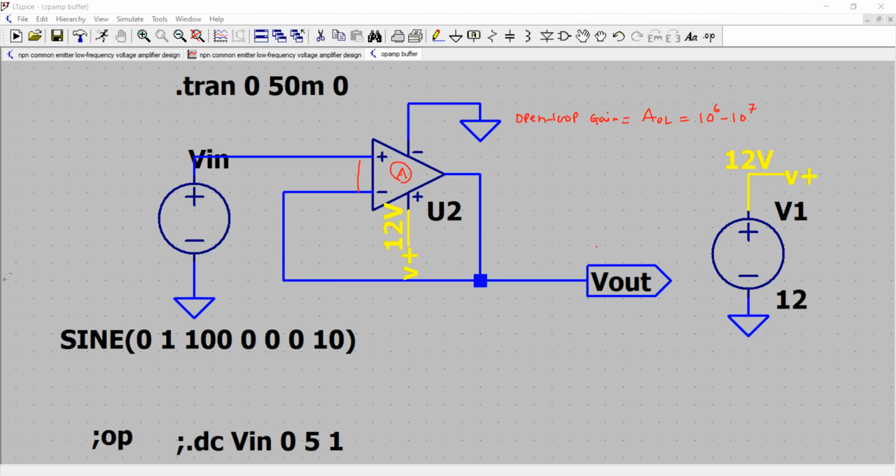So with that said, I just told you why I use the universal op-amp, because I can set my own gain, I can set my own gain bandwidth product, and I can set an offset voltage, which is set to 0 in this case. Now, how this circuit works, that's the main question here. So you see, to the positive input I have this input signal that is coming. It could be a DC voltage or it could be an AC voltage.